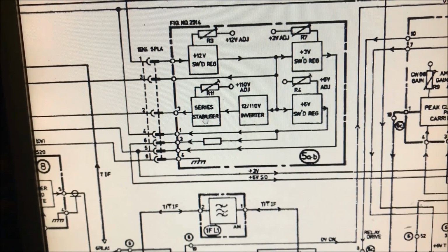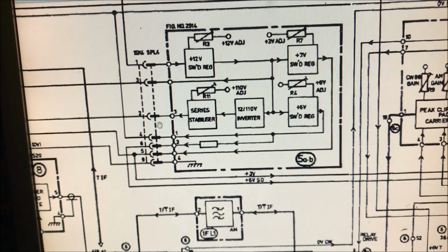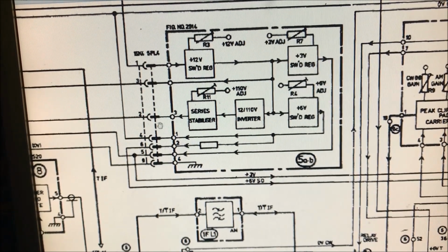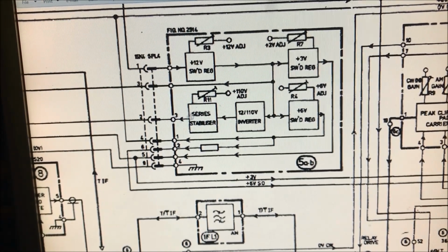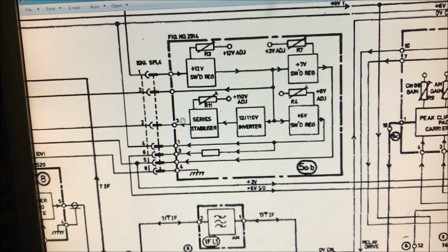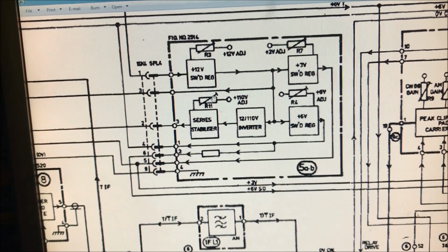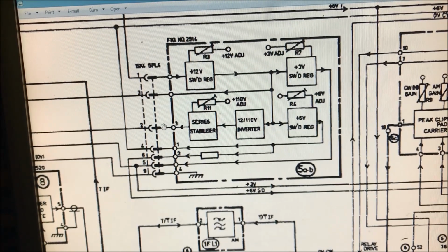So you need to be looking at the voltage coming out of your power supply and make sure it's a stabilized voltage around 110 volts. So there's a little twiddle adjustment, there it is right there, and as you move that up, the voltage will slowly increase and decrease when you move it back down again, and it's recommended to have it about 110 volts.